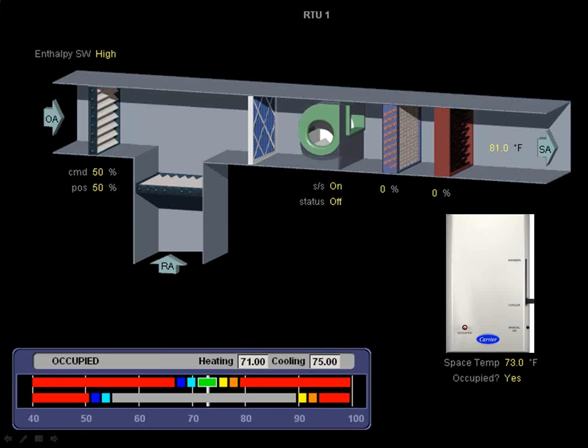But his question was related to a bypassless zoning system for Vision Pro Redlink. The Honeywell zoning systems do use bypass dampers. The no-bypass systems were the early ones we talked about, the Carrier Infinity and Bryant Evolution, because those systems are talking directly to the fan blower and can change the fan blower's speed. The Honeywell system does not do that because they'd have to be able to talk to every single manufacturer of every single blower, which would be very hard for them. So they still use a bypass.